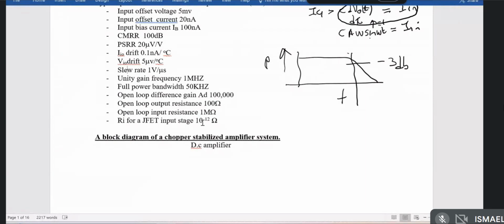But when we are concerned with voltage amplification, we just want the resistance at the input of the amplifier to be much, much greater than the resistance of your source, so that most of the voltage will appear at the input of your amplifier. So if your source resistance is high, you need an amplifier with a high input resistance. So you can use a JFET input or a MOSFET input.